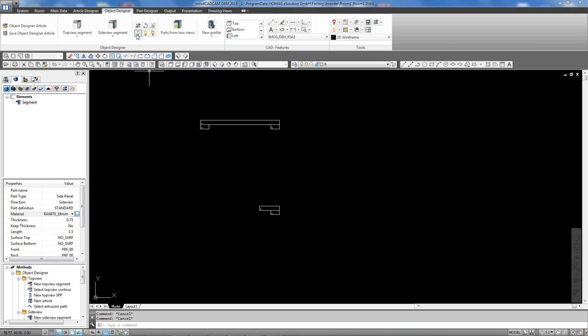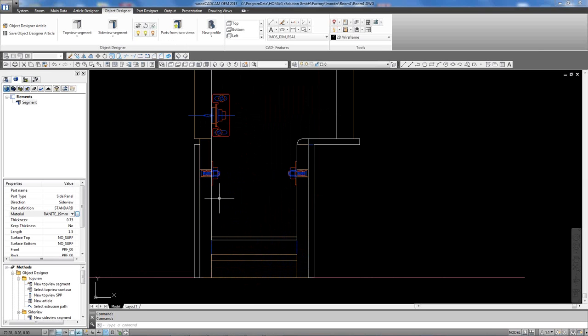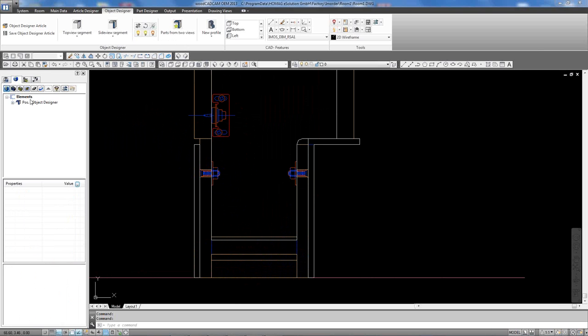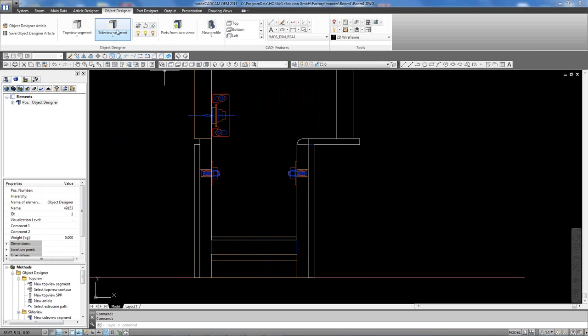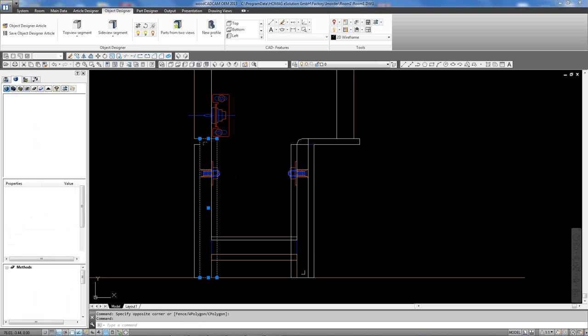And then you just go on and create all your parts. I'm going to turn my other things back on. If I have a part such as down here that are not a 3/4 material like the others were, they're a 1/2 inch material. So you see when I draw the segment, my segment's actually bigger than what my original is. So I say to myself, okay, this is actually a different material.